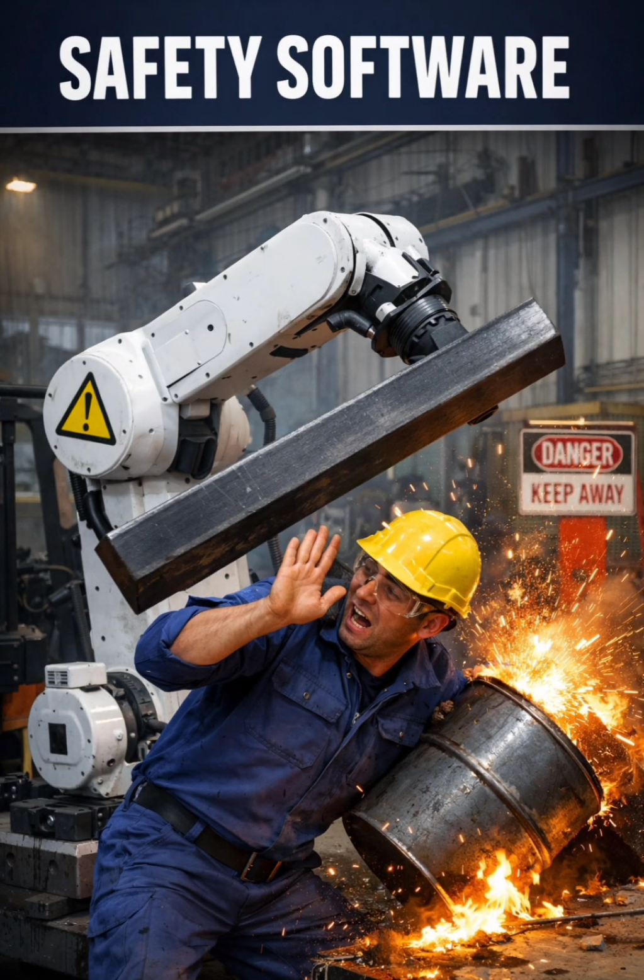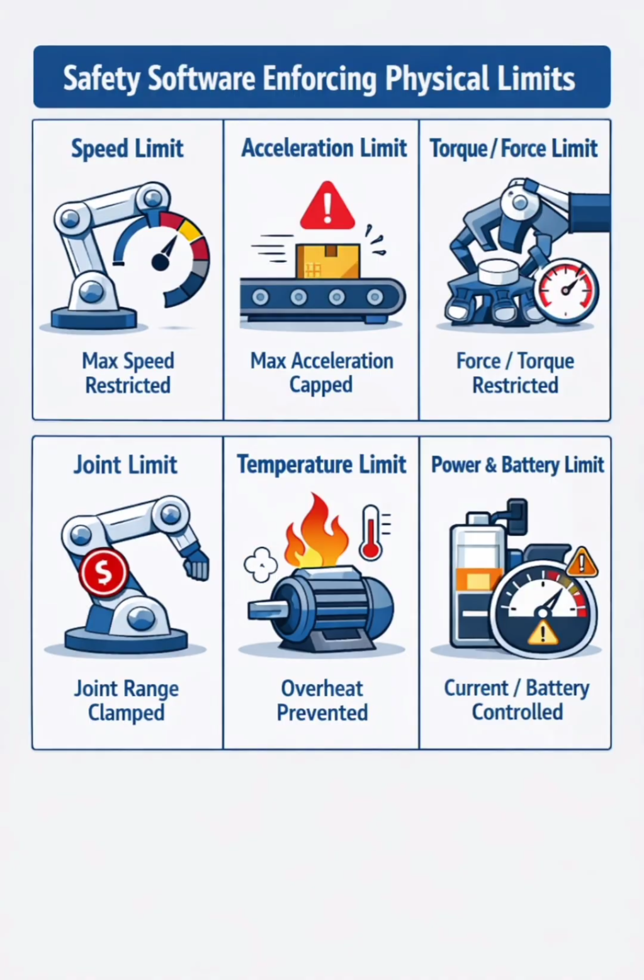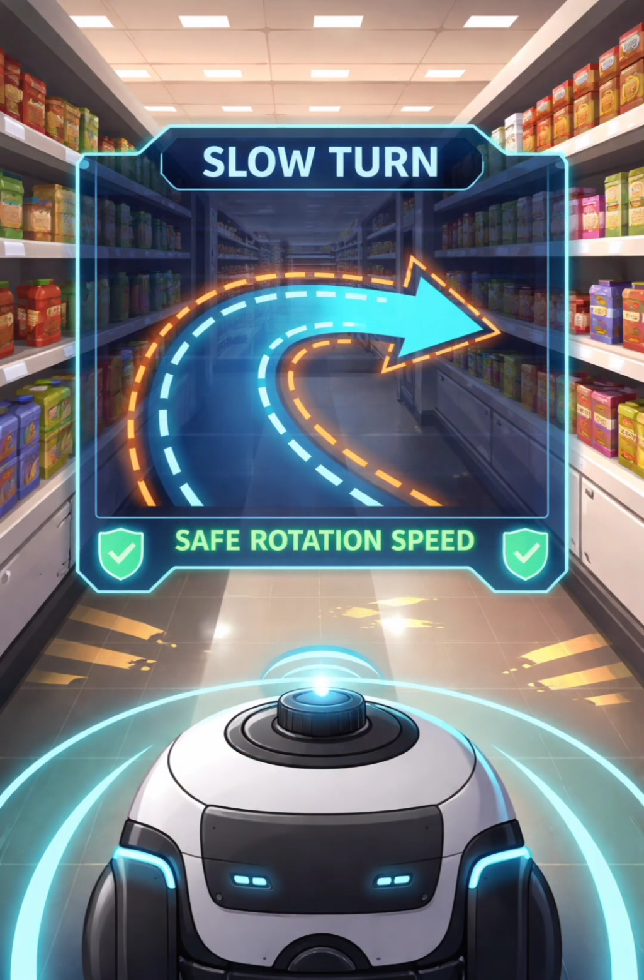Safety software is the part of a robotic system that prevents hazardous behavior even when other modules make mistakes or hardware faults occur. It acts as an independent supervisory layer that enforces hard limits and triggers safe states. In practice, safety software does four main things. First, it enforces physical limits. It clamps or blocks commands that exceed safe bounds: maximum speed, acceleration, torque, force, joint limits, temperature, current, and battery constraints. Example: if navigation asks for a fast turn near a shelf, safety caps the angular speed to a safe value.